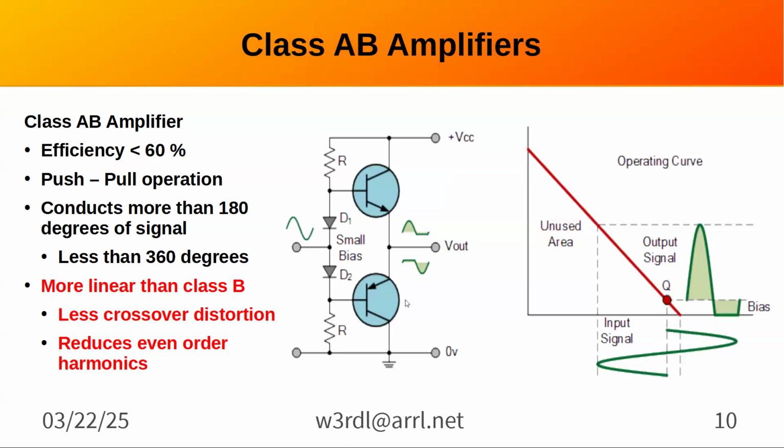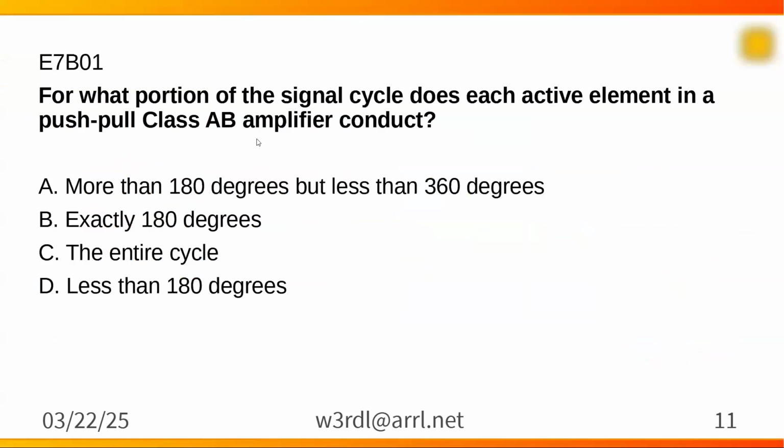I don't think the circuit would actually work as is. It would work, but the input signal would have to be biased above ground. If those diodes were germanium, it wouldn't really be an AB amplifier. No, unless you had germanium transistors. Or if you had gallium arsenide, then you might have too much.